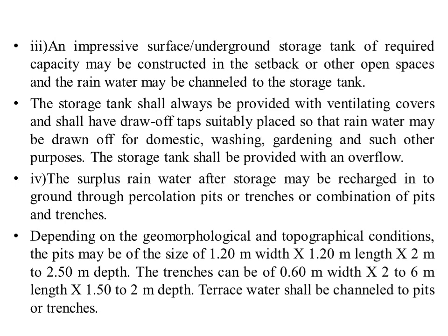For example, for hospitals, 100 liters per capita per day is the requirement of hot water. Similarly, for hotels, 150 liters per capita per day. For hostels and other buildings, 25 liters per capita per day. Canteen as required. Laboratory, research institution as required. An open area of 3 square meters should be required for installation of a collector which supplies about 100 liters of water per day. At least 60% of the roof area may be utilized for installation of the system.